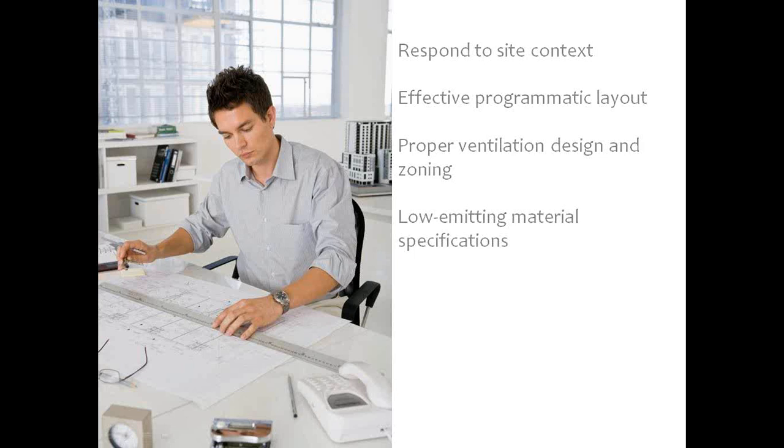Same thing applies to healthcare. When people move into the emergency room, you definitely don't want that air to be shared throughout the intensive care unit, the surgical unit, the neonatal care unit. So programming, how you actually lay out the space, and ventilation, how you decide how to zone it so that it is ventilated properly and adequately, is key.